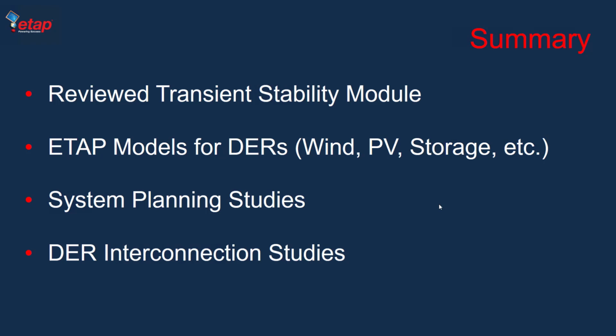At the same time, sometimes the generic model is also useful, where it's the earliest stage of the project, the vendor has not been picked, or the black box model may not be available. So we support those kinds of generic models, with which you can do more detailed studies of FRT curves and low voltage ride-through capability, tripping of the circuit breakers and timings, and how much active and reactive power will be injected to the system.